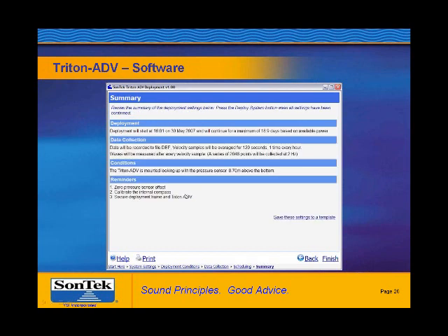Okay, going back to that last summary page, if you are connected to a live system, you get a couple of additional options. One is to transfer the settings that you've set up directly to the system, and another is to deploy the system. At the bottom of that summary, you can also see a number of reminders. These are some of the standard steps that we suggest people go through before they deploy the system: zeroing the pressure sensor, always calibrating that internal compass, preferably in the mount, but sometimes that's not always possible, and then making sure that the Triton is actually secure inside the frame.